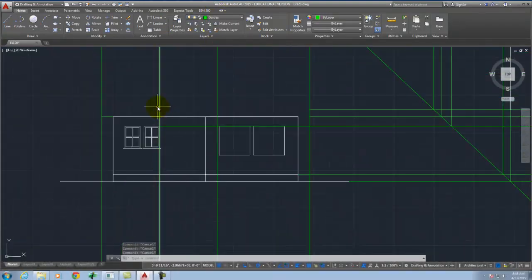All right. So now the next piece of the puzzle is I need to know what the slope of the roof would be, right? And so a standard slope would be maybe a 6 and 12, right? Maybe a 4 and 12, depends on the style of the building. If you were trying to do more of a cabin, maybe you'd do something that was all the way up to a 12 and 12.